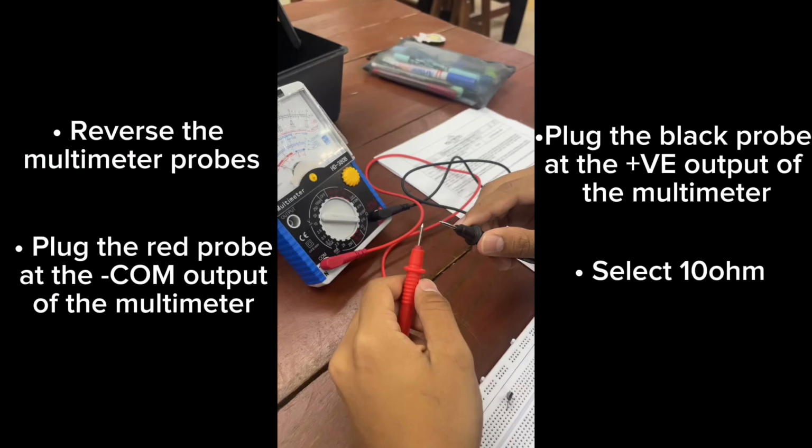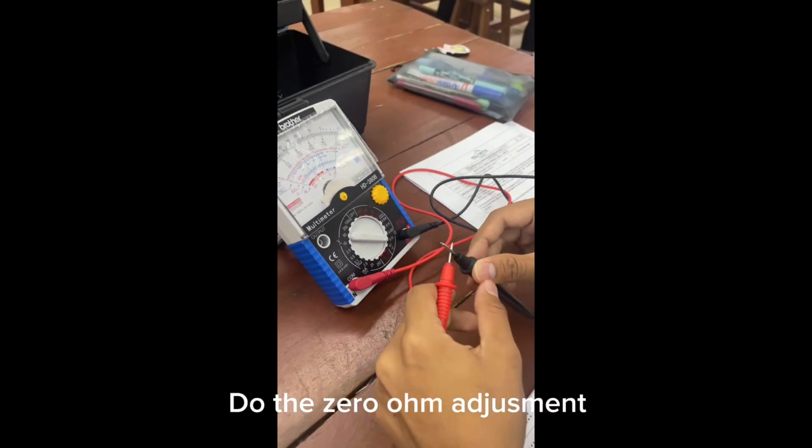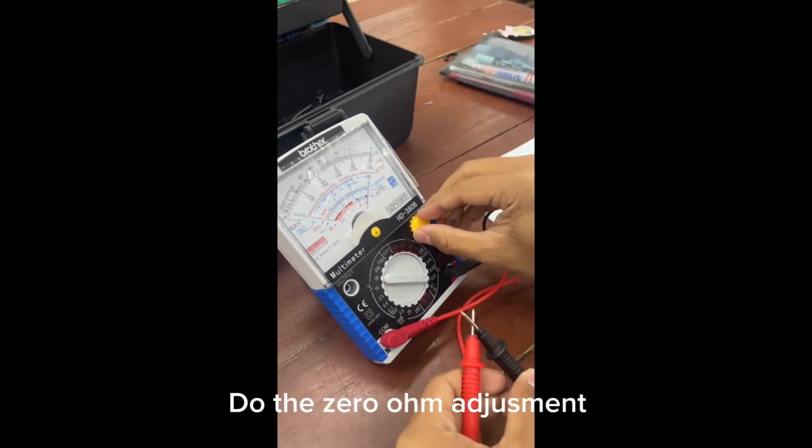First, reverse the multimeter probes. Then plug the red probe at the negative COM output of the multimeter, and plug the black probe at the positive output of the multimeter and select 10 ohm. Next, do the 0 ohm adjustment.